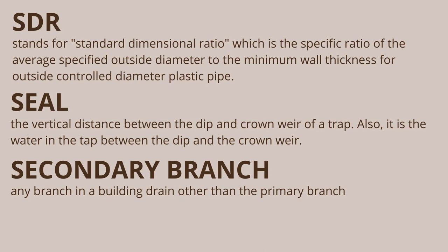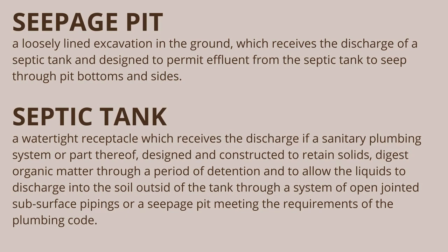Secondary branch. Any branch in a building drain other than the primary branch. Seepage pit. A loosely lined excavation in the ground, which receives the discharge of a septic tank and designed to permit effluent from the septic tank to seep through pit bottoms and sides.